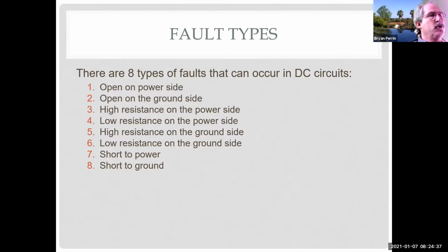Just like if I have a short, I could have a short to power, or I could have a short to ground. If I'm shorted to ground, I'm probably going to blow a fuse. If I'm shorted to power, my light bulb might not ever turn off. So there's 2 kinds of short, Mr. Brian. Yes, I can be shorted to power or I can be shorted to ground.